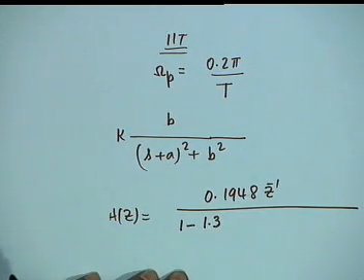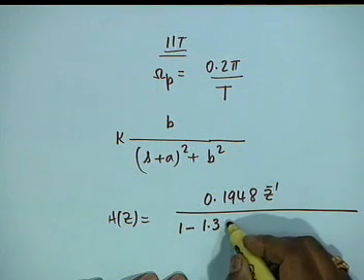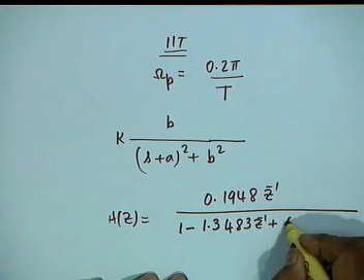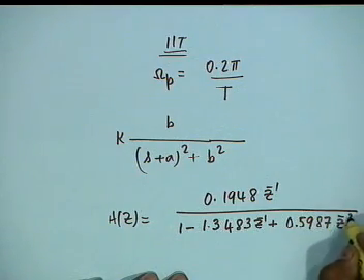The final result will be the same form, except that we do not have 1 plus z inverse whole square. Agreed? At pi it is not 0. The denominator is 1 minus 1.3483 z inverse plus 0.5987 z to the minus 2.